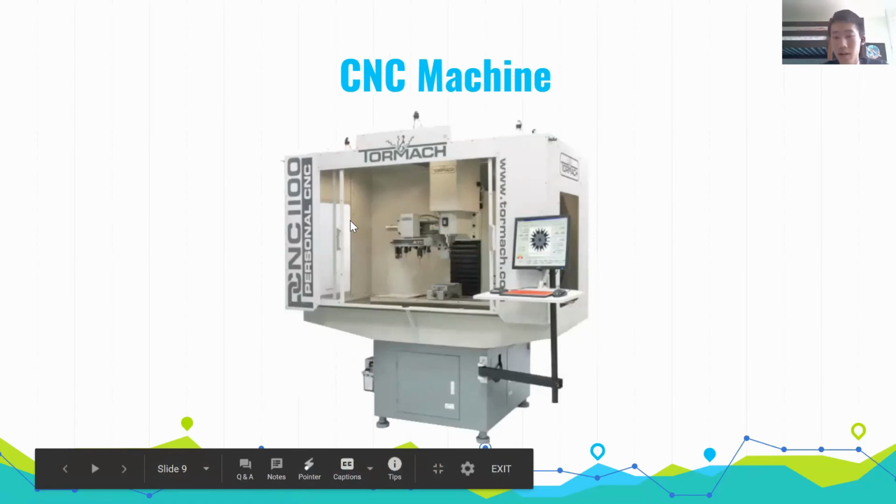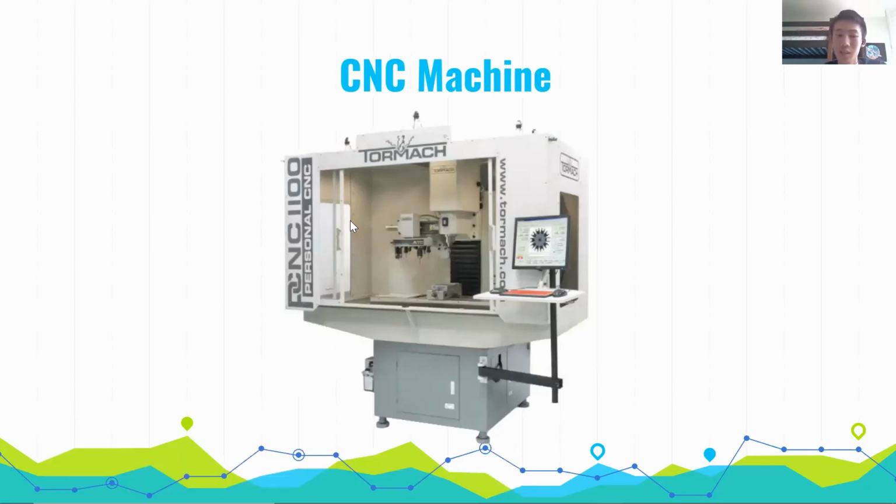And the third one is CNC machines. CNC machines use a drill bit to carve out shapes in materials like metal. If you want to cut something out of steel or aluminum, a CNC machine is probably your best bet. It will take some time to cut because, again, it is carving out layers of your material, but to make custom metal parts, it is probably needed. And of course, to use a CNC machine, you're going to have to learn how to CAM, as that is how the machine reads your program and converts it to the part.